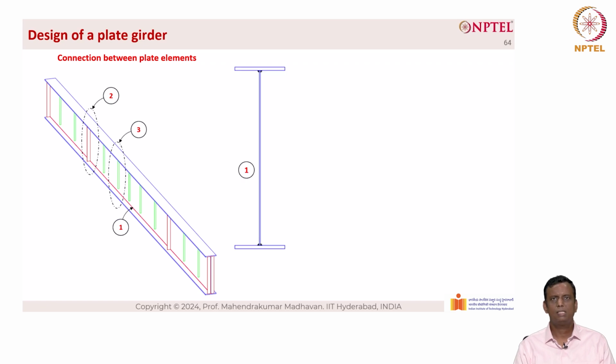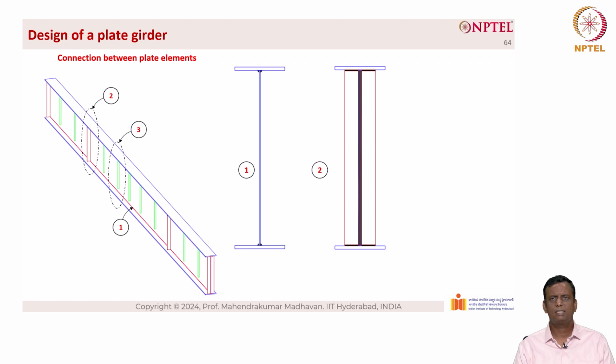Here we can closely see the welding between the top flange and the web as well as the bottom flange and the web on either sides of the web. Next is the bearing stiffener, and we can see the weld location of the bearing stiffener highlighted here, both on either sides of the web as well as the top and bottom flanges. So if we cut a location AA, we can see section AA which shows you the weld locations, and at section BB again it shows you the weld from the top flange view. We can see a cruciform cross section with welding on all four directions.